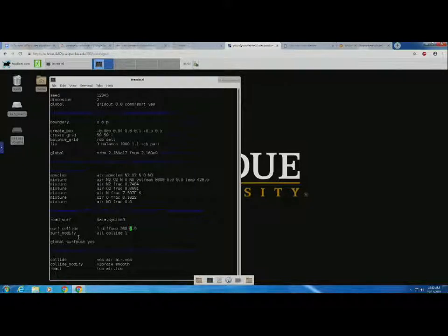For the condensation coefficient, if it's 0, it's basically a specular collision or a specular surface. If it's 1, that means it's perfectly diffuse, and a more realistic number is 0.9, so it's usually 90% diffuse. And then this is saying that the surface is going to be at 300 Kelvin. And then all particles that collide with the surface collide according to my ID number, which is called 1, and that's the ID here.